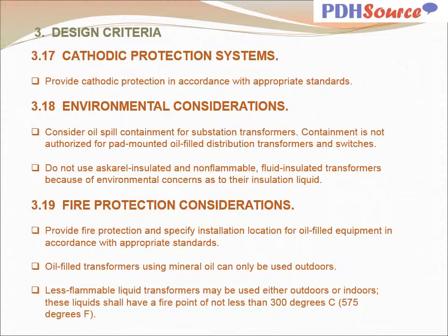Consider oil spill containment for substation transformers. Containment is not authorized for pad-mounted oil-filled distribution transformers and switches. Do not use Ascarel insulated and non-flammable fluid insulated transformers because of environmental concerns as to their insulation liquid.